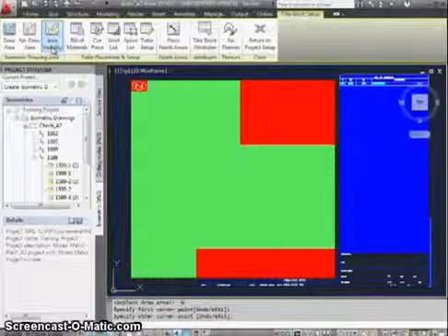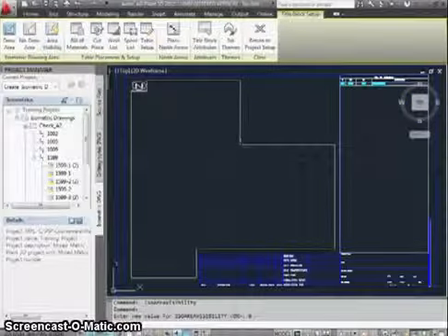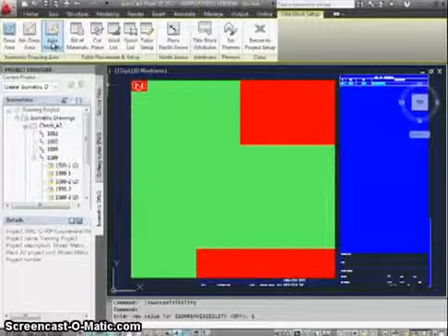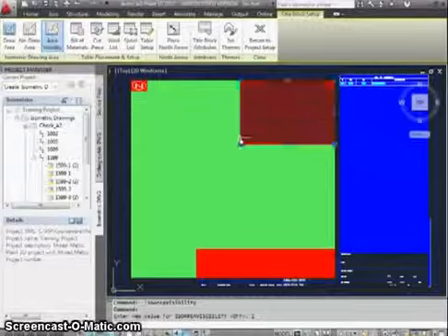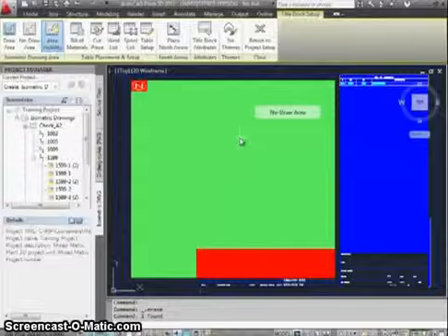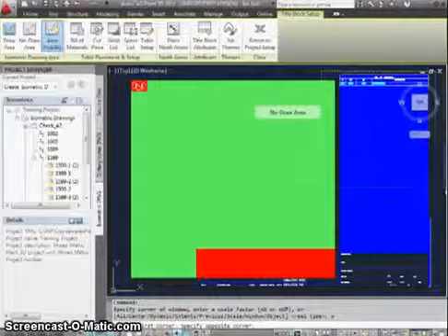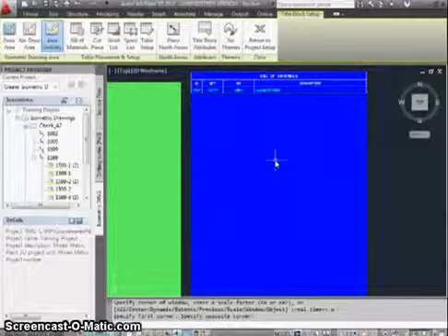You can display ISO areas as a perimeter instead of a hatch. In the ribbon, turn off area visibility to draw at the perimeter. But to edit areas, they need to be displayed, so let's turn visibility back on and remove the new no-draw area. The blue area to the right is the table area, where we place table parts.